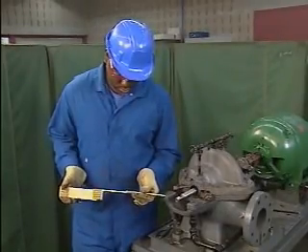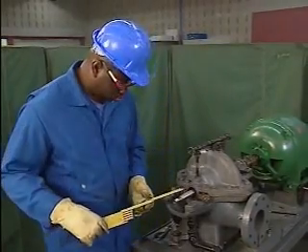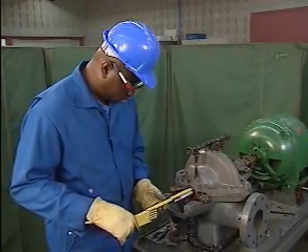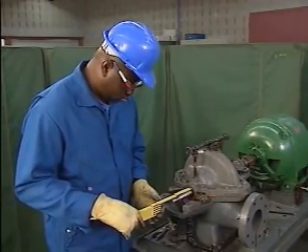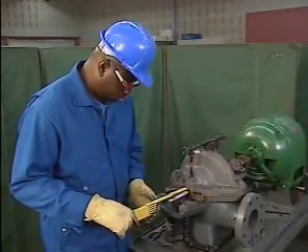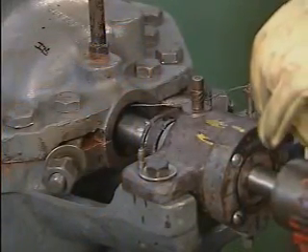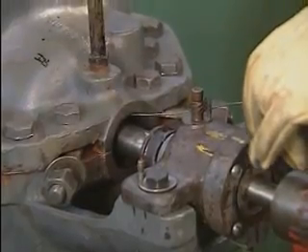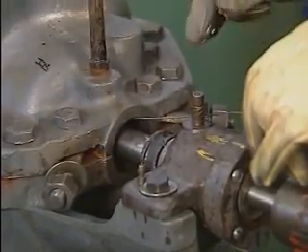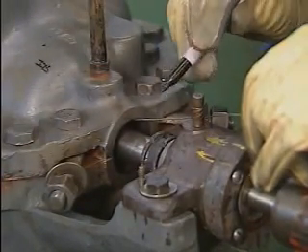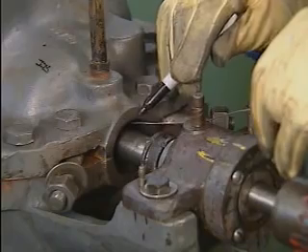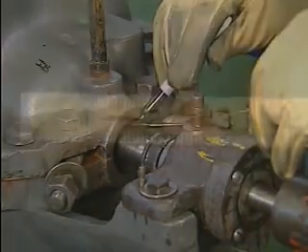Next, the mechanic uses a ruler to measure the depth of the stuffing box to determine how many rings of packing will be needed for this installation. The depth of the stuffing box is the distance, top to bottom, parallel to the shaft. On some applications, it's not possible to directly measure the depth using a ruler. Instead, the mechanic inserts a stiff piece of wire into the stuffing box and marks the depth on the wire.